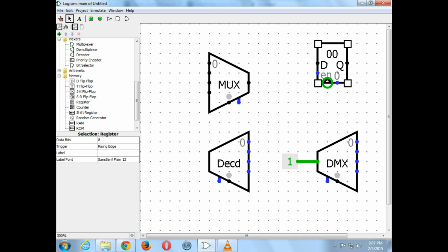Would you be able to make the computer more efficient if you can manipulate the other transition? Not really, because the whole point of a clock in a processor is to synchronize the operation of all the different components. And typically, what you do with a register is when you update it, you leave a little bit of time for the register to quote unquote settle down. And once a register settles down, the output will reflect the actual content.